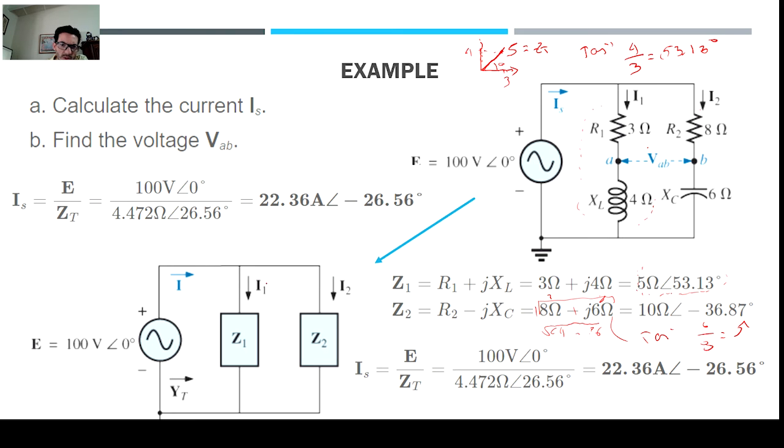And since the voltage through this leg is the same as the voltage through this leg, we can use Ohm's law at this point. And to use Ohm's law, we need to compute the total impedance, which we can get from Z1 and Z2, the impedance from the first combination and the impedance from the second combination, and they're in parallel.